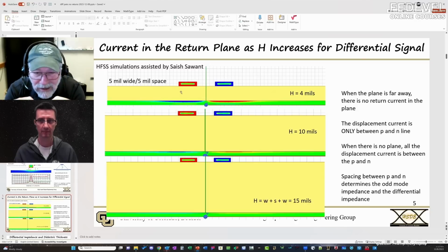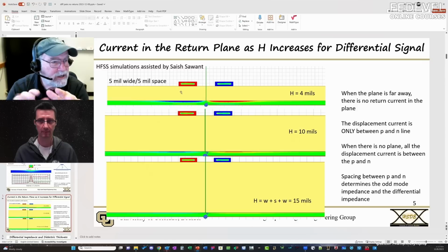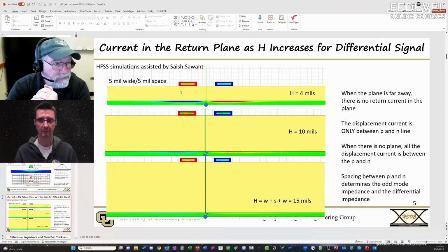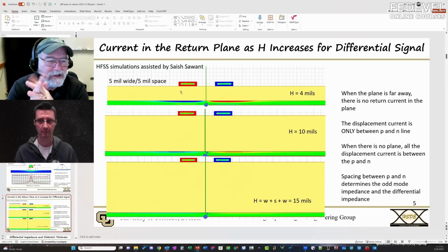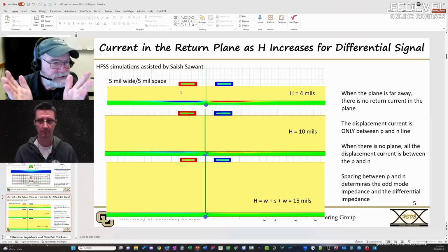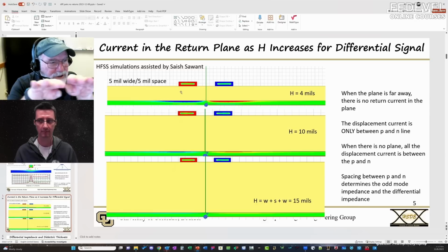And if I use uncoupled, as I move them farther, I'll use a wider line. And at some point, that means a little less loss. And so if I live for loss, maybe loosely coupled is a better trade-off of interconnect density and loss. It turns out that crosstalk, I hear a lot of folks saying, well, I want to use tightly coupled differential pairs so that I don't have a lot of crosstalk or I reduce crosstalk in this differential pair from another differential pair. Totally wrong.